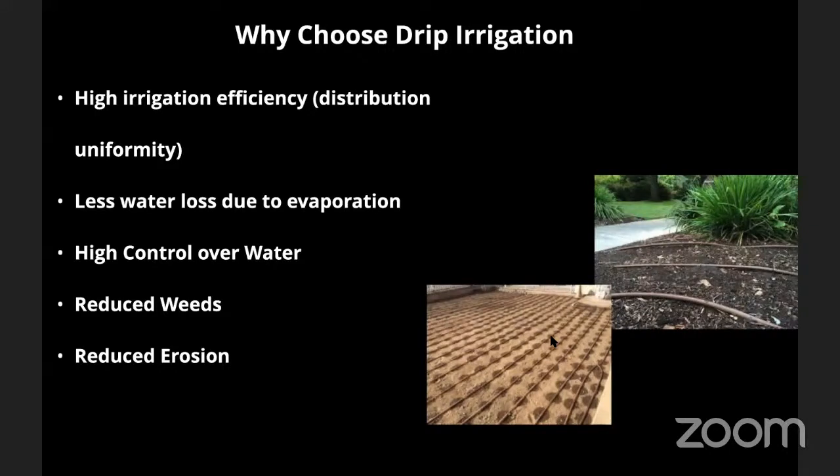And if you have a mixed garden that has trees and shrubs and all sorts of other things, you don't need to worry about something closer to the sprinklers that's taller being hit by the sprinklers and having an area behind that plant that remains dry, because the drip goes underneath everything. Because that water is not flying through the air, it doesn't evaporate. That evaporative water loss is minimized to essentially not there, which is big. I mean, if you have overhead sprinklers, you should be watering in the evening anyways.